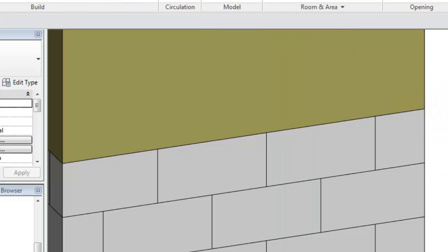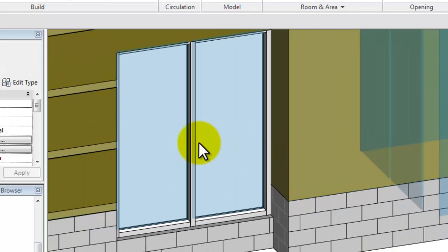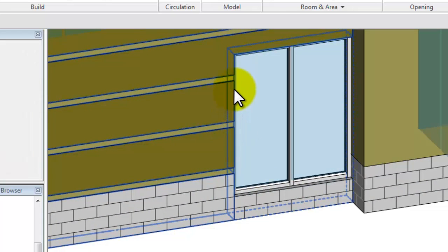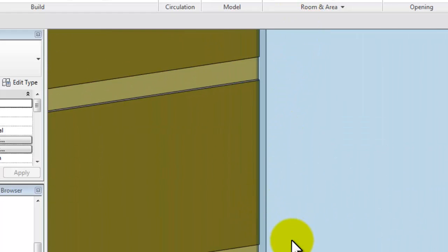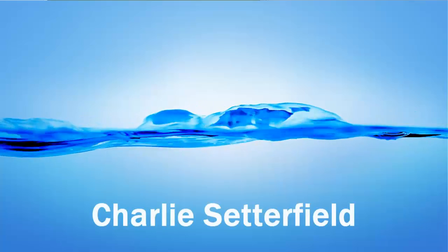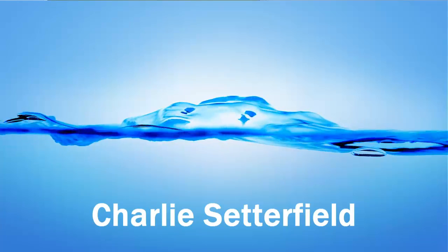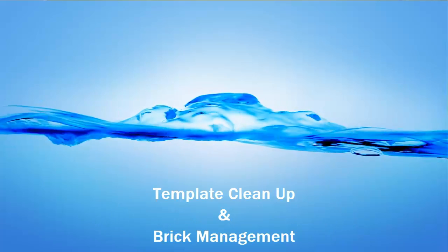So now I've got a smooth transition. I've got the right size. But if everything worked OK on the other parts of the building, I still have my reveal. That's what I was after. Yep, still got it. I was after this reveal that happens with the accent brick over there. So the strategy is to have 2 different wall types with 2 different thicknesses of brick on them, and that takes care of that situation for us. So we'll stop there and move on to something else in the next video.